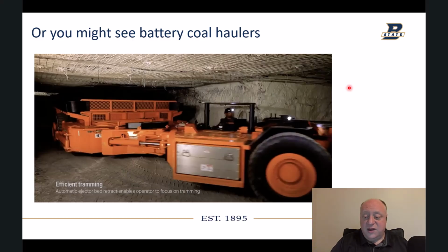They operate in this sort of cyclical fashion. After they leave the dump, they're coming back up to the miner, loading up, and then running this way. This is mainly due to the way they're loaded and the way they articulate. So you end up needing one or two more to get efficient production out of coal haulers in that cycle, because it's not a straight line.